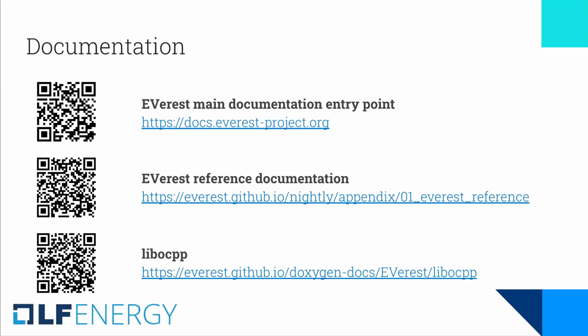Next is a multi-part question. What OTA update mechanism does EVerest use for its embedded Linux-based controllers? Start with that one. I think I can take this one. So EVerest itself doesn't give you any restrictions on what to use. We have successfully used RAUC in some deployments, but you could use basically anything that does updates.